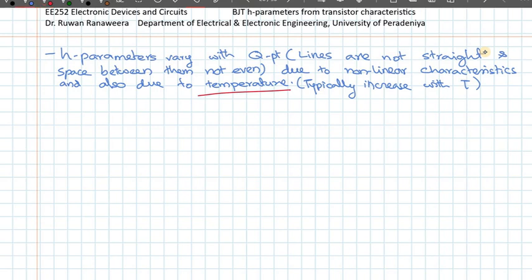Okay, so let me give you a summary of what are some typical values of each of these parameters for different transistor configurations, amplifier configurations. So far what we have looked at is only the common emitter parameters, HIE, HRE, HFE and HOE, but this will be similar to other configurations also, like HIC, HOC, HFC, HRC, and the common base parameters will similarly be affected.